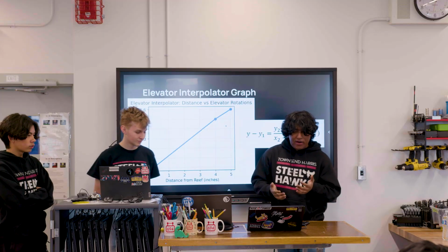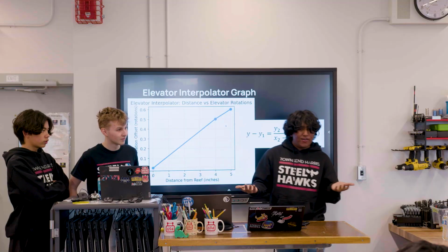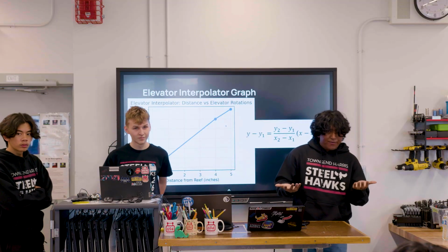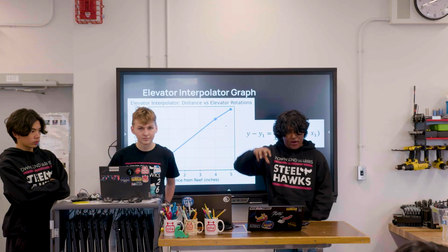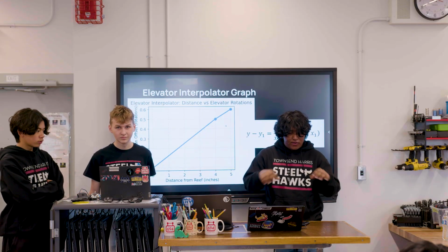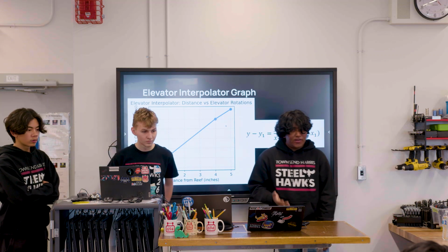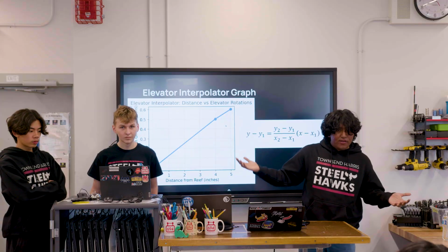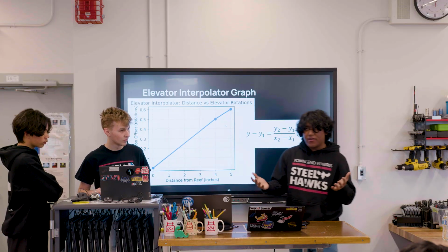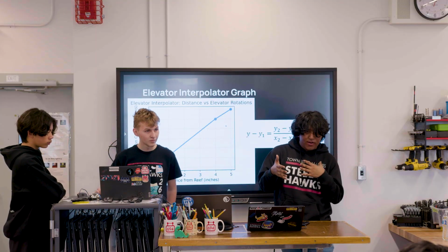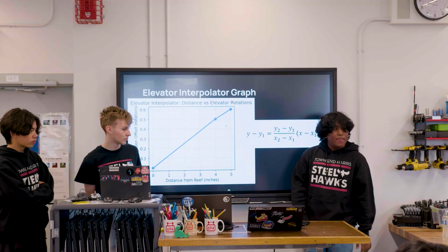So we're gonna have a code snippet, and we can show you. But you just use odometry, because you know where the reef is. You know where your robot is. You would just calculate where your claw is. You would add an offset because your odometry is in the center of the robot, right? Once you add that offset, you just find how far the branch is, right? Something we'll get into in a little bit is, since now your distance is changing, your initial velocity when you shoot the shooter has to change. And we'll show you how we get our range using that. Any other questions?